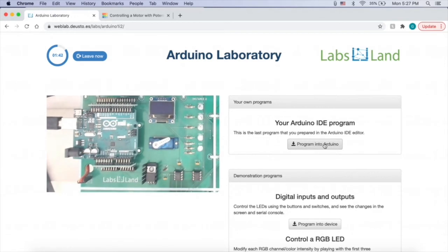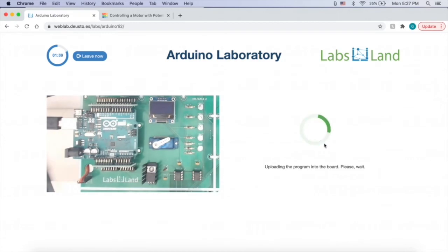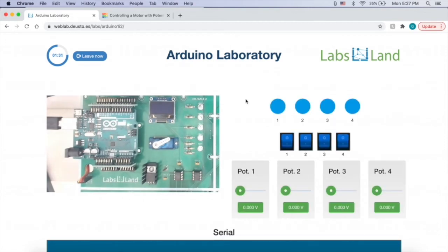And for 2 minutes you can program your code into Arduino, and once it's programmed, it should be able to have the functionality you have designed it to have. So I have designed it to have the buttons 1 and 2 as the controlling buttons, and they will in turn light up this LED blinking red or green. So let's see, this should blink the red LED twice. There's some delay with the video right now, but this is not the case normally, but you can see that the red LED is turning on, and similarly the green LED should also turn on like this.